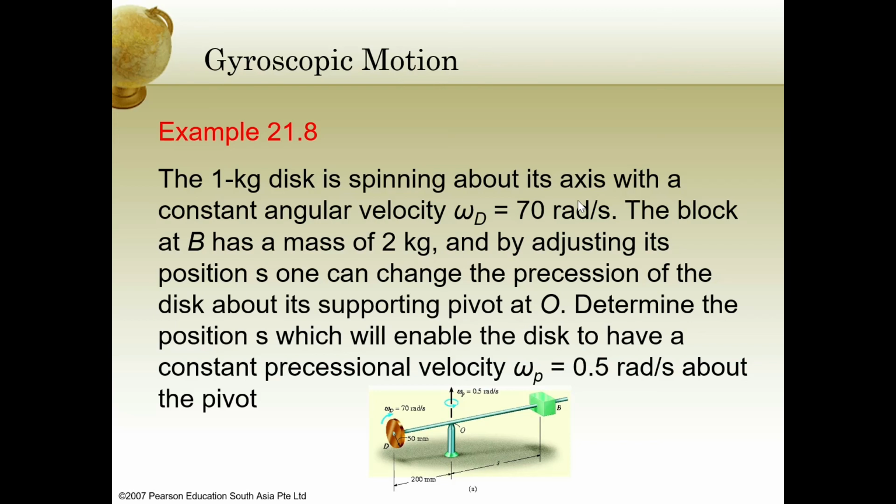Because the precession motion is this way, the vertical line from the origin is the precession axis, which is the big Z axis, and the spin axis is the horizontal line along the shaft. So that's the small z. That means the nutation angle is 90 degrees.